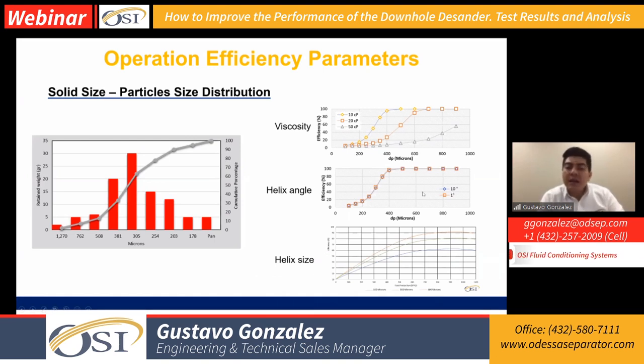And we see that regardless of whether we change that angle or that inclination between 1 to 10 degrees, we're going to see around the same centrifugal force through the system, because everything is more related to the drawdown that I'm generating, or how hard I am pulling that fluid, and based on the differential pressure that I have on my system, that's what is going to create that centrifugal force. So the angle was not a major factor for this particular case and this particular sample that we were evaluating.